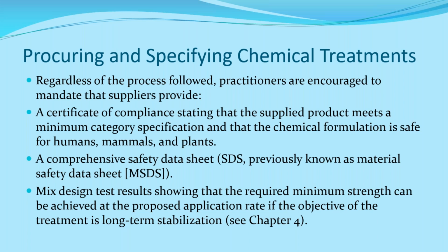And you also then have to continue doing your seal coats, or like they did in South Dakota, where they came in and took some of those types of roadways and reground the road material back up, mixing it into the subgrade a little bit, and then made them into a gravel road again. But you've got to make a decision on what type of properties you want that roadway to have.